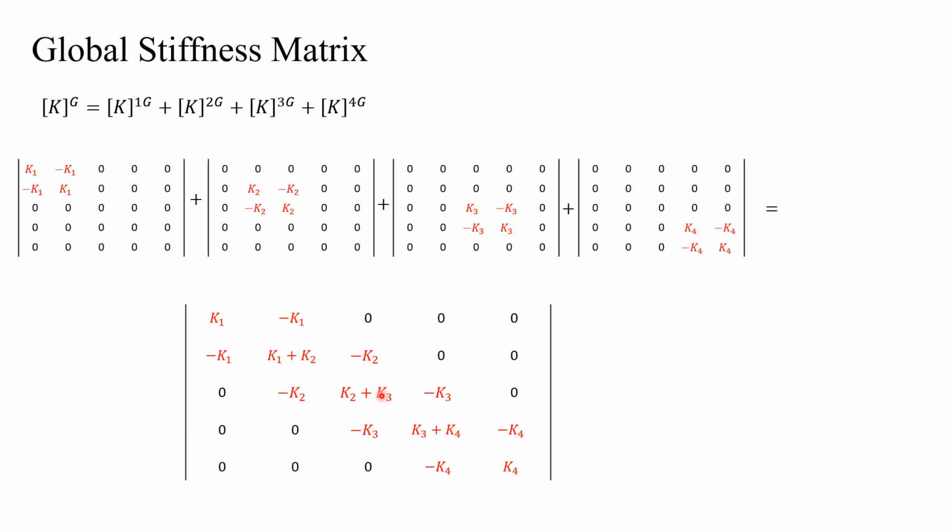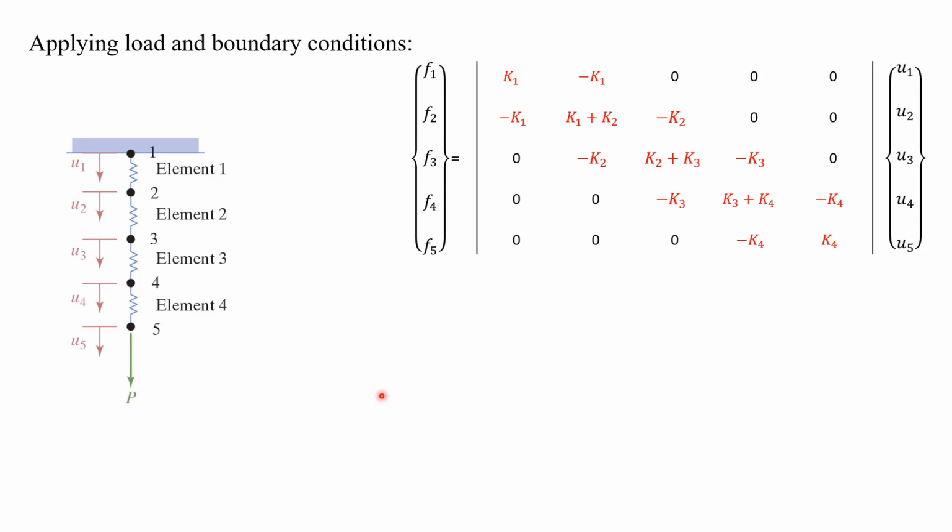And we found this stiffness matrix in a direct form. We just drew the 3-by diagram, found the local stiffness matrices, wrote them in a global form, and added them together to get the global stiffness matrix. Many approaches that we use in FEA for different elements are to find this global stiffness matrix. After this, whatever we talk about would be applicable to all elements and all approaches. So the next step is to apply the load and boundary conditions.